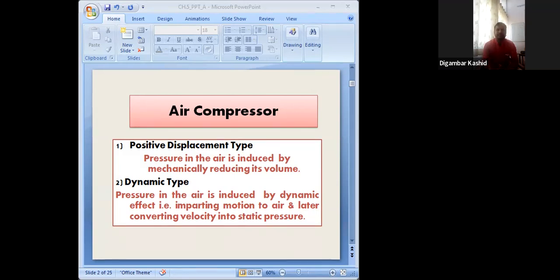You need to check whether your compressed air is clean and in a safe condition. For this purpose, fluid conditioners such as the filter, lubricator, regulator, muffler, and air dryer are required in the pneumatic system.